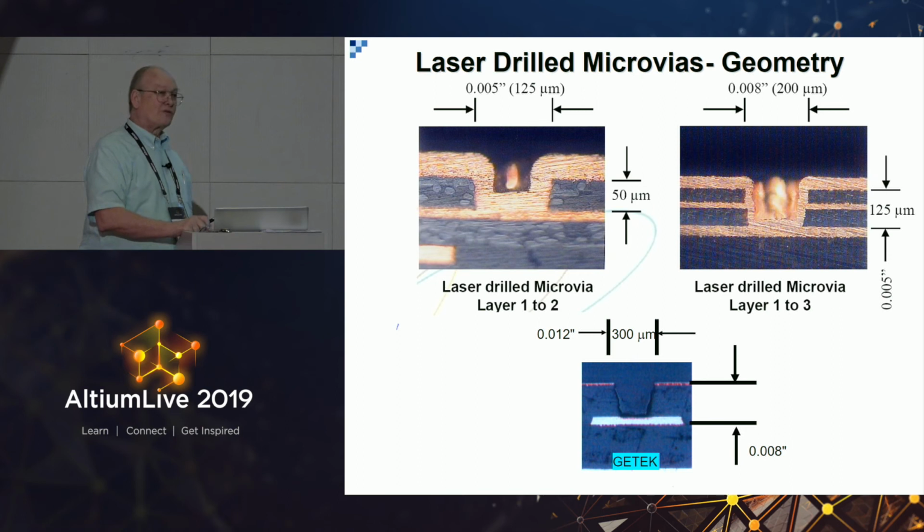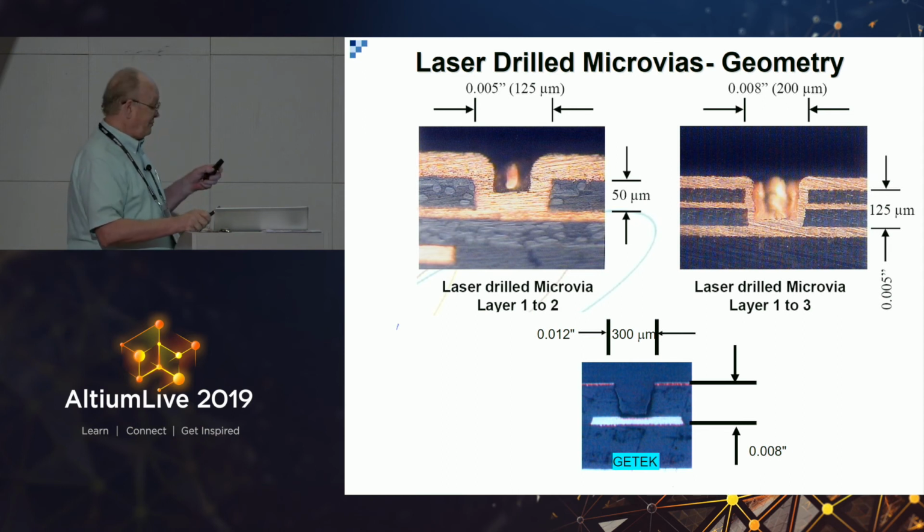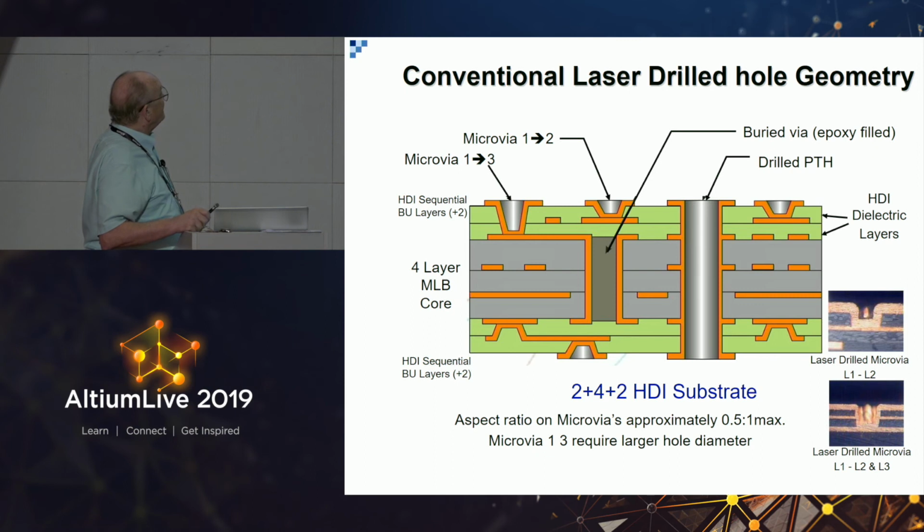Really difficult to work with, but anybody familiar with G-Tech, the old, I'm trying to think of a Ventec equivalent. Well, the only equivalent is the Megtron 6 and Megtron 7 material, the expensive materials. So, we're going to talk about different aspects of how this guy and this guy replaces this guy and this guy.